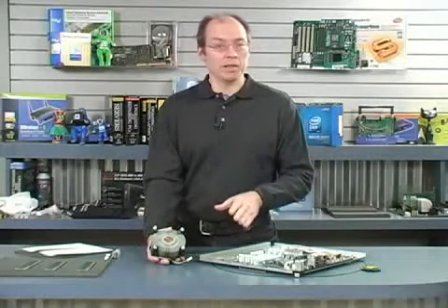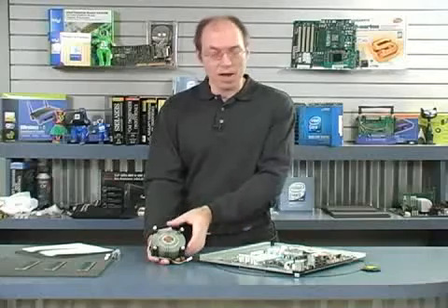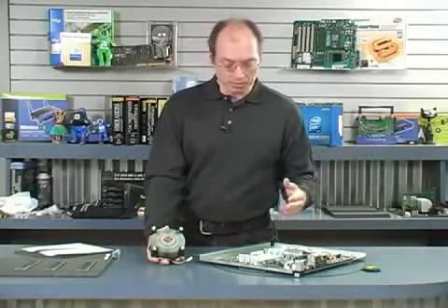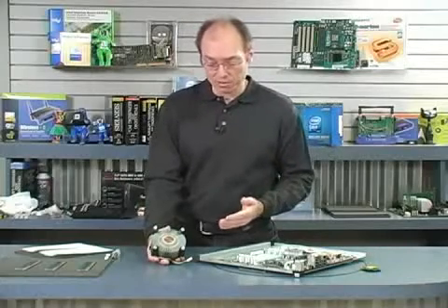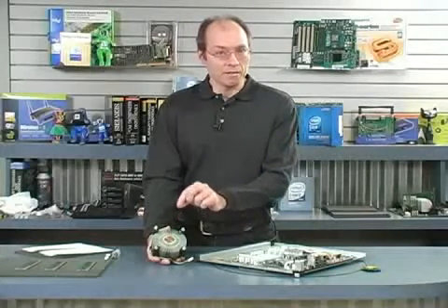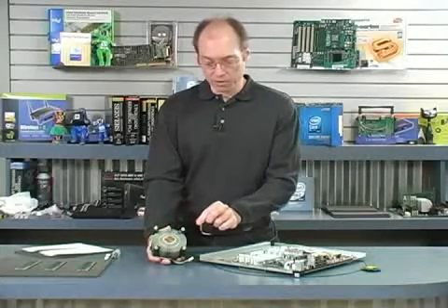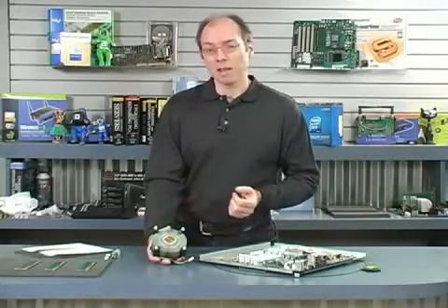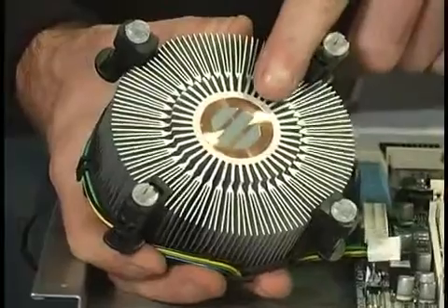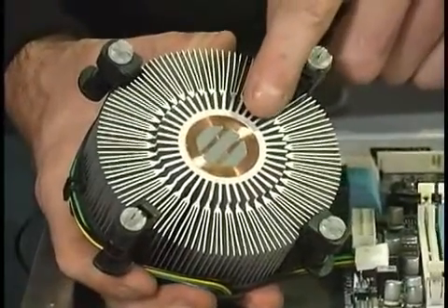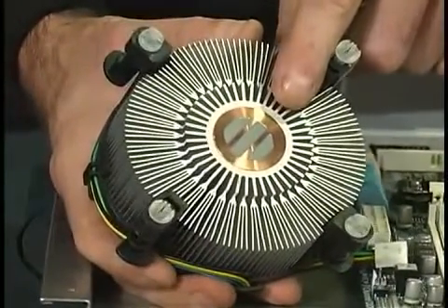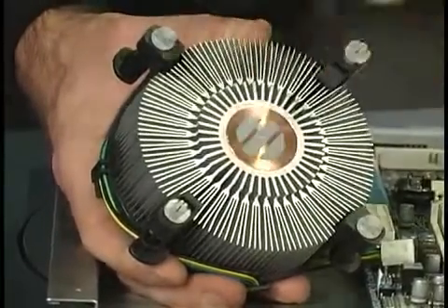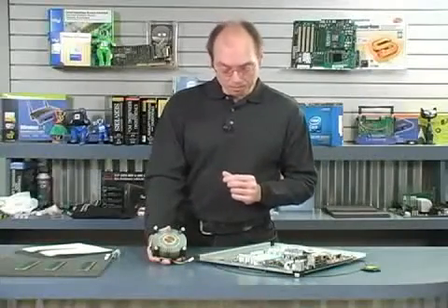When companies like Intel and AMD deliver their boxed processors with the factory included heatsink, to make the installation as easy as possible, they will pre-apply a phase change type thermal interface material to the bottom of the heatsink. I'm going to show you an example on the screen right now of what that looks like. As you can see in this example, there are 3 bands of material, and it's a waxy type material. You don't want to touch it. You want to keep it protected until you actually install it, because you can damage it with your finger.